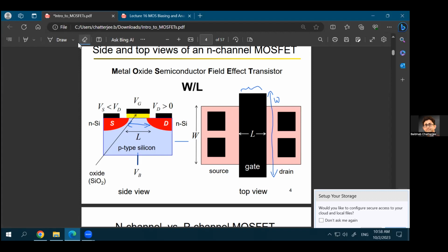Okay, exactly. So that's a great question. Since it was already drawn, I should talk about this width. If you take a fabrication technology class for a MOSFET, on how to actually fabricate this device, you'll see that there is a concept of active area, that you dope a certain area of the device, and then you start creating the source, gate, and the drains.